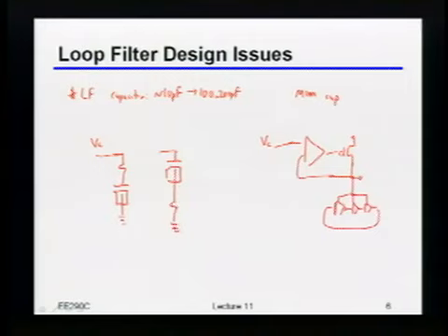You have a lot of ground capacitance. Yeah, I have the bottom plate, right? So on this one, I have a bottom plate cap that sits right there. What's bad about that bottom plate cap? What does it do to you? That's one more pole. Yeah, it adds a pole, right?